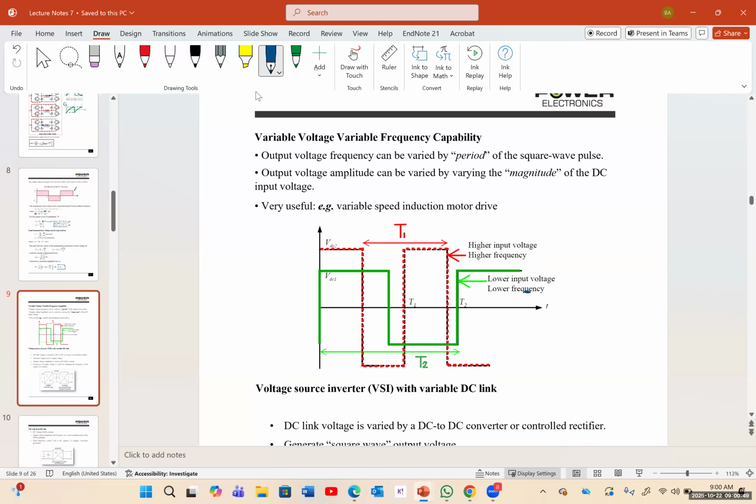I wanted to put an inverter, and after that, I could put a transformer. But the problem with that was that even if you put 1 volt in the input, the transformer is going to boost that, and you have to find the threshold on when the chopper and also the DC to AC works. But you're going to see a lot of these problems in the real world and senior design, and you have to come up with a genius way to solve it.